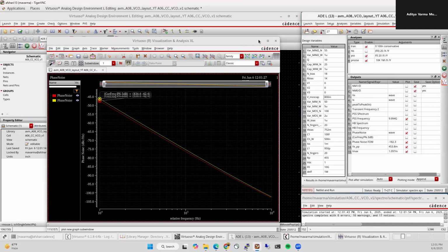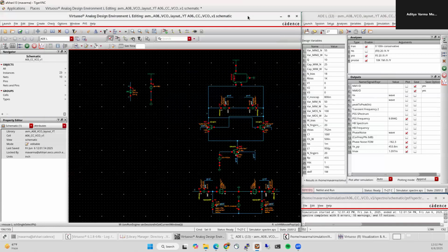I said the fringing capacitance decreases. It's the other way around. When you do the layouts, the fringing cap kind of increases, right? You have parasitics added in. That's why, because of those parasitics, we'll see that this actually shifts down a little bit. So right now it's going from 10 to 10.7. We want to bring it to 9.7 to 10.3. So once you do the layout, because of the added parasitics, this will actually shift down a little bit.